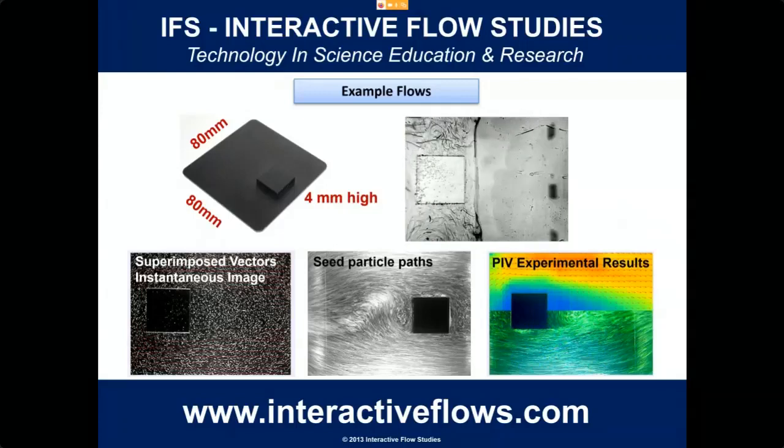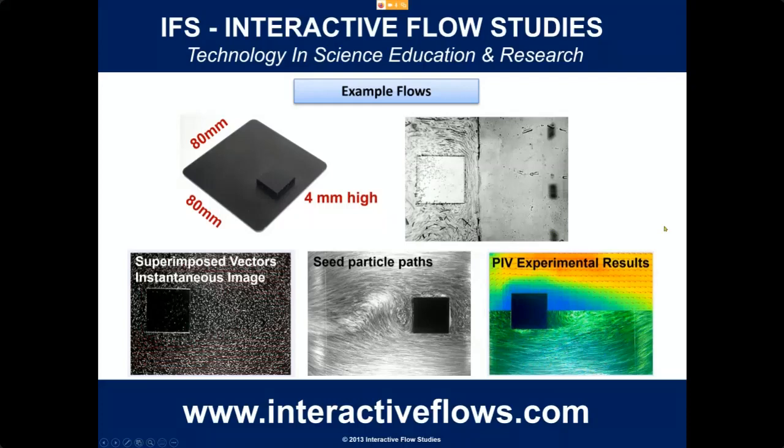That's the self-cleaning feature that cleaned up the surface there. And the middle one, again, if you control the exposure and so on, you can get all kinds of images. And this one, I think, is an average of all the images. The bottom right-hand corner is the PIV experimental results, actual velocity vectors and shaded diagram. The shade, I think blue is slow and red is fast.